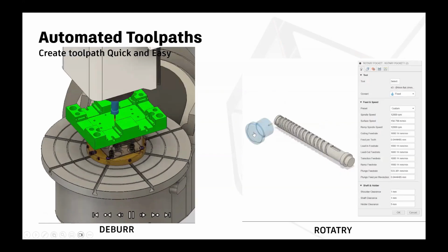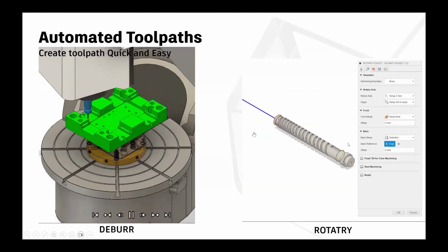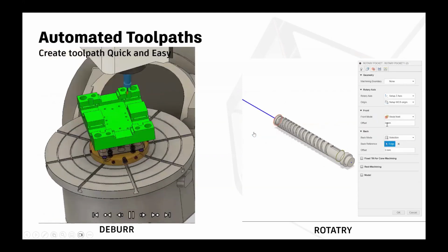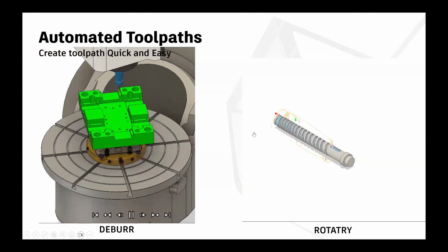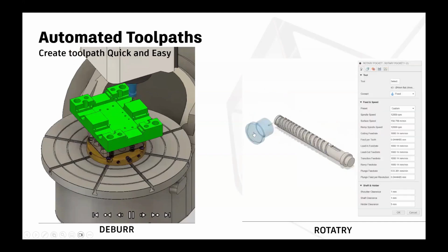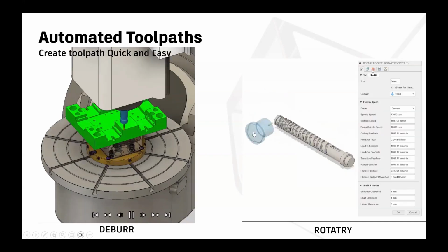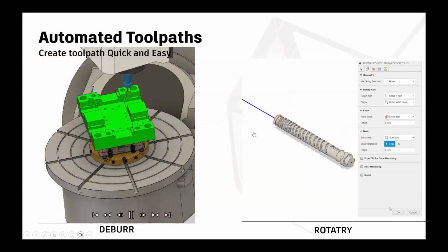Second one is the rotary toolpath, where you can just select the start and end, and it will identify where the pockets are which need to be machined, the fourth axis pockets, and it will create a very nice fourth axis toolpath. Now this also has another variant for contouring. So if you want to finish the walls or if you want to finish the floors on it, it does the same thing but with your finishing operations.